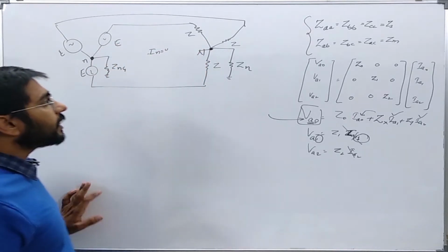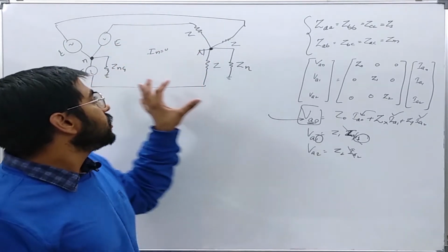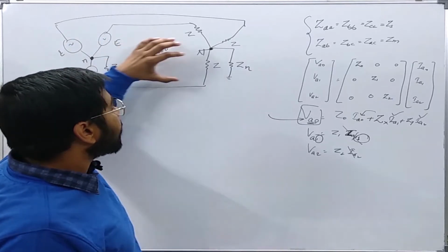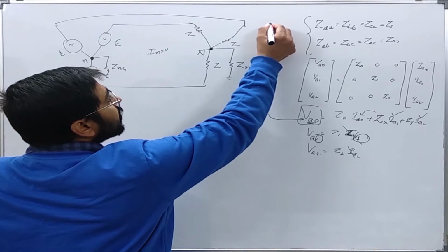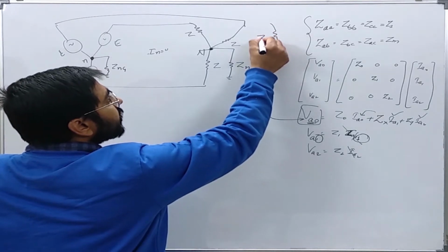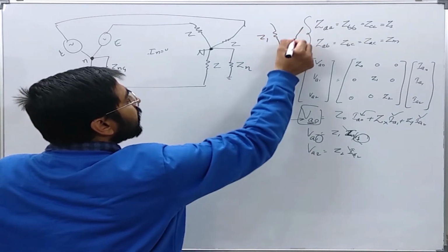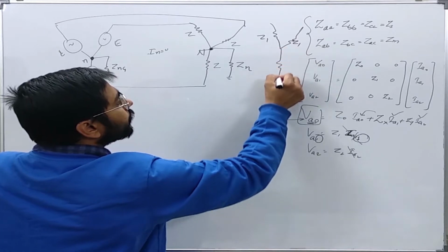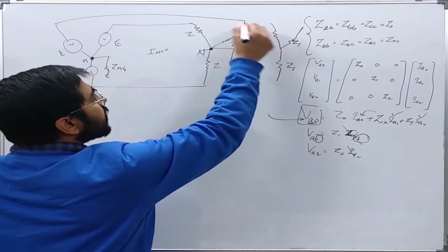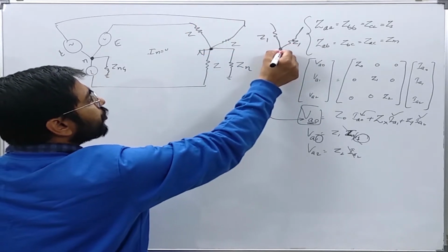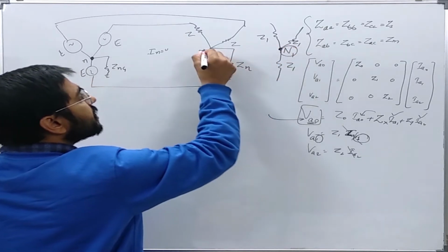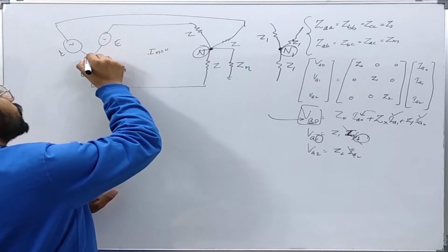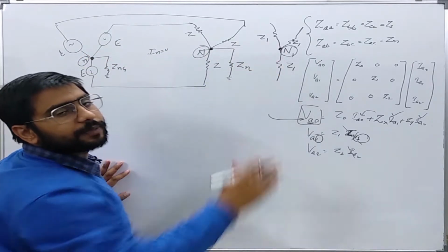So in such a scenario, even if I add some other load which is again symmetrical and balanced, then this neutral point, let us say N1, will be at the same potential as the other two points if it is connected to the power system.